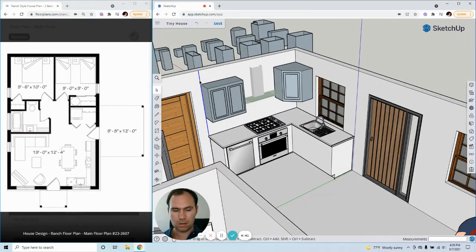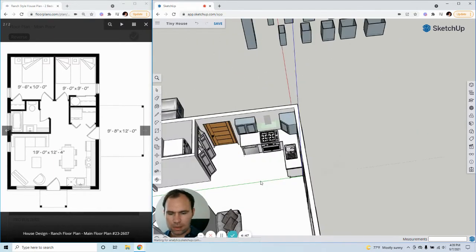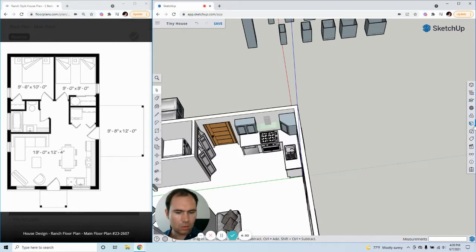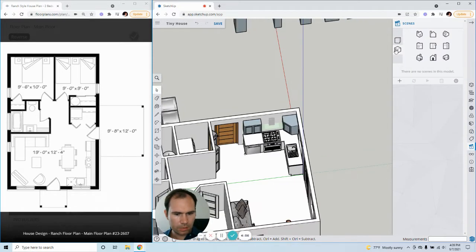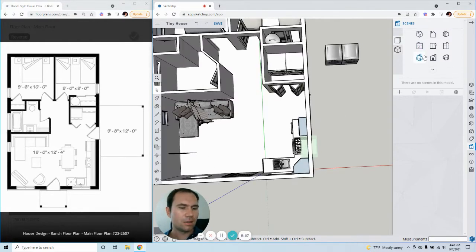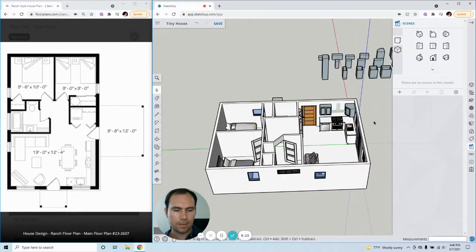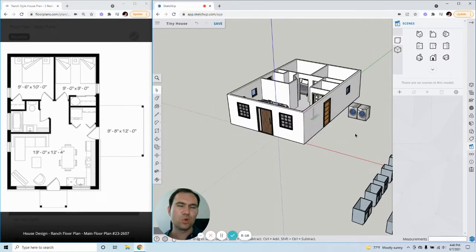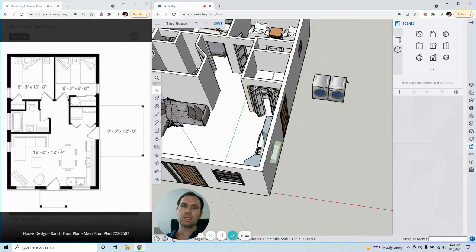And so let's delete the lines we don't need. If we look at our floor plan on the left here, that matches. And we can even go to display, to parallel projection, top view. Kind of matches our drawing. Another pet peeve I have about SketchUp is they don't provide the door swing in parallel projection. That's proven to be a missing feature, but we can live with it.